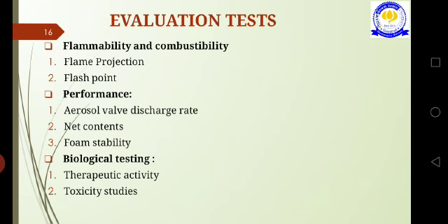To assess the risk factor as well as the performance of those propellants, we have to perform the flame projection test and flash point test. These two tests are very important in case of aerosol preparations.